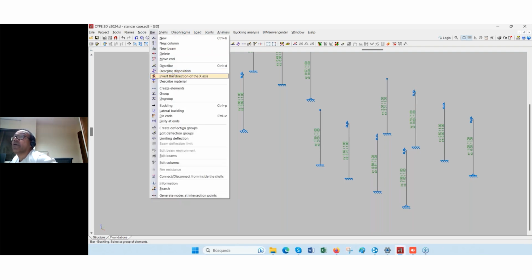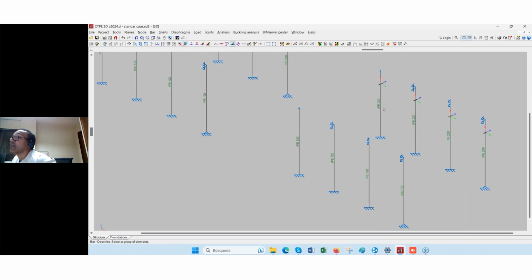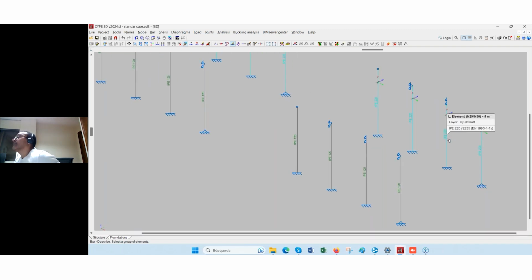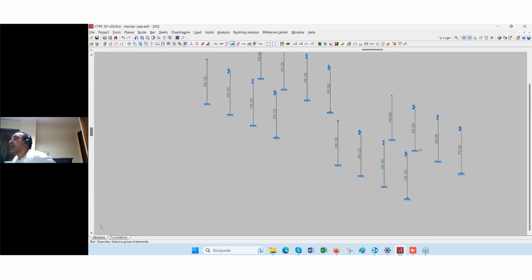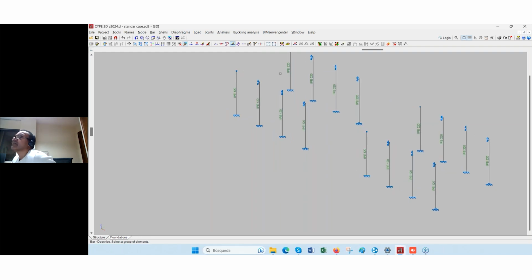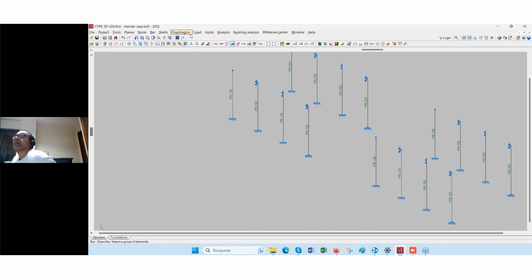At the back point, when I described it, you see that I have a very big section. This big section avoids the deflection from the shear forces. So that's why we have exactly the same value we got theoretically. That means that taking into account the self weight of the bar and the shear deformation gives you a slight difference with the conventional way of calculating.